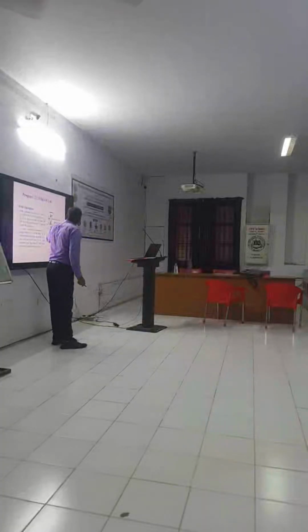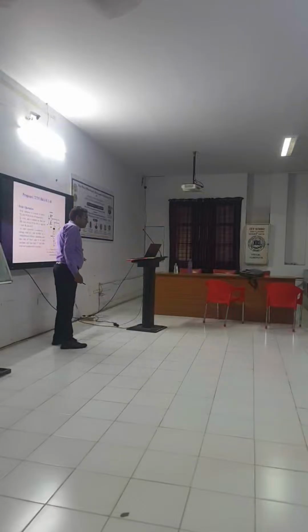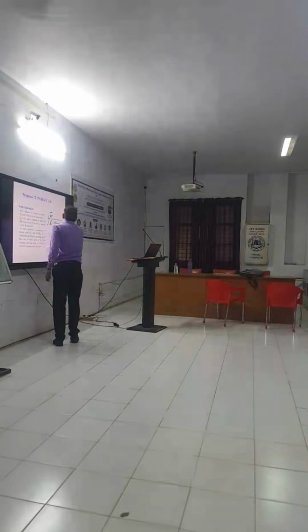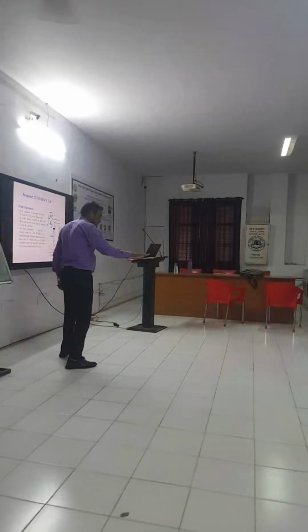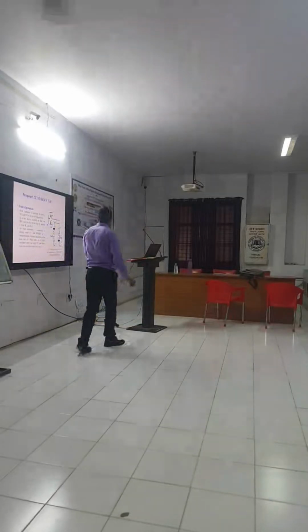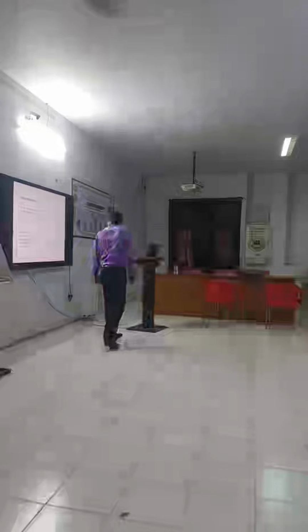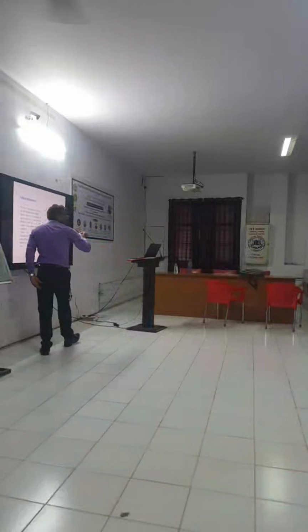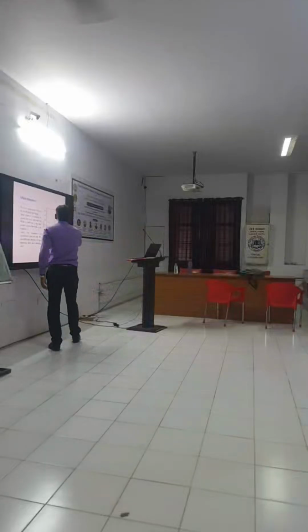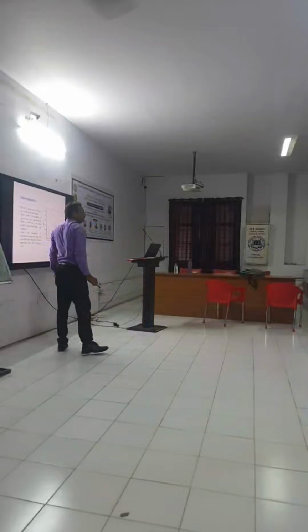So here 1, here 0. So here it will become a less resistive path. What will happen? Less resistive means it is like a short circuit. So this BL starts increasing, while BL bar remains the same. BL bar remains the same because it starts at 0, and BL increases to 1.